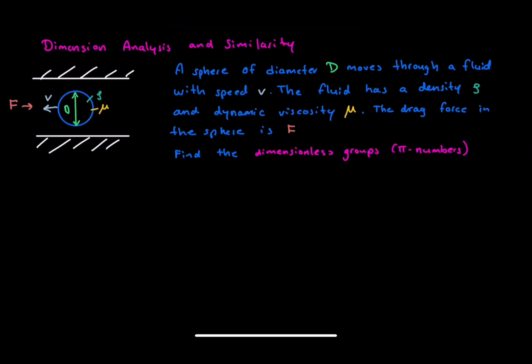Good morning, champs. Today, we're stepping back from equations and going one level deeper into how we systematically build them. This is about dimensional analysis, similarity, and why numbers like the Reynolds number appear everywhere in fluid mechanics. We're going to solve a full problem using a Gauss-Jordan style tableau because this is the most systematic and least error-prone way to do dimensional analysis. Once you see it, you won't guess exponents ever again.